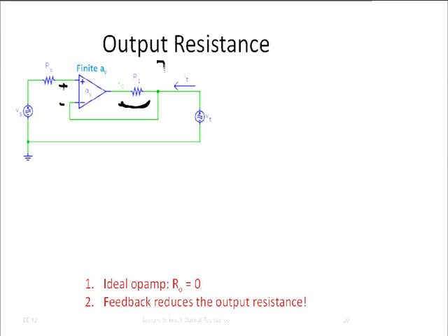So if I look back into my operational amplifier, what is the output resistance? What does that mean? Well, a circuit having finite output resistance means basically that when I pull more or less current, then the voltage changes, right? It's just like a Thevenin equivalent, where R Thevenin is not zero, like very often is the case. Then the voltage that we get from such a source, of course, depends on the amount of current we have.